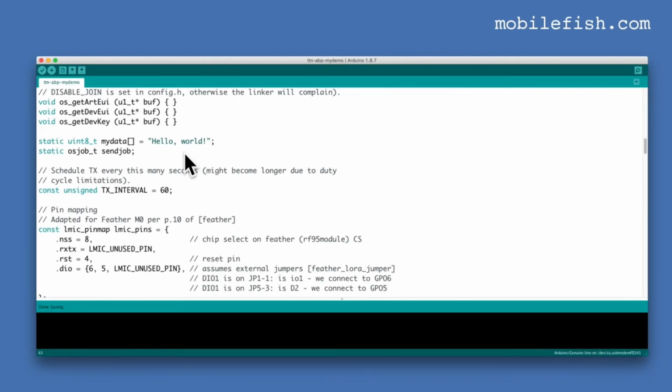Same as in tutorial 22, the message Hello World is transmitted every 60 seconds. If we use this transmit time interval, we will not comply with the Things Network Fair Access Policy. If we run the sketch for more than 24 hours and the data rate is spreading factor 7, bandwidth 125 kHz, or even worse, spreading factor 12, bandwidth 125 kHz. Please do the calculations yourself.